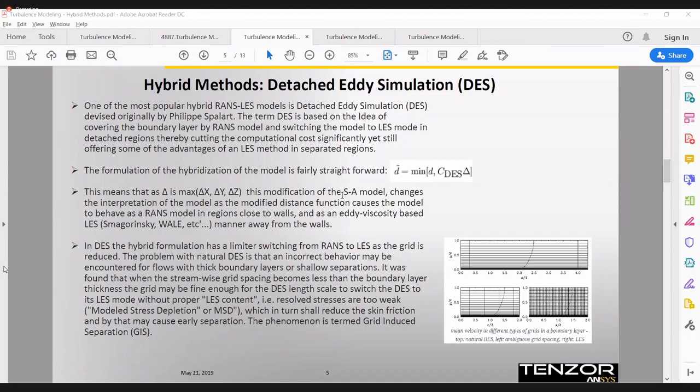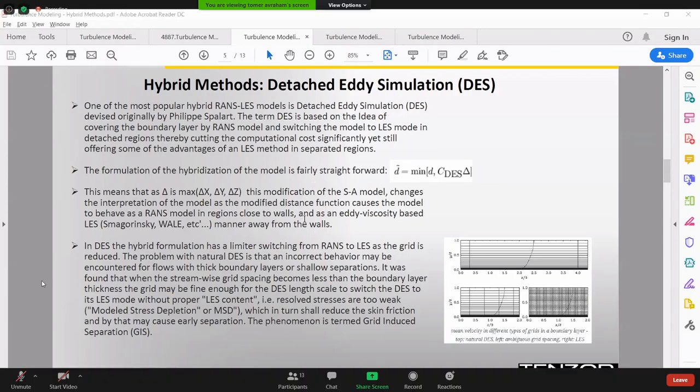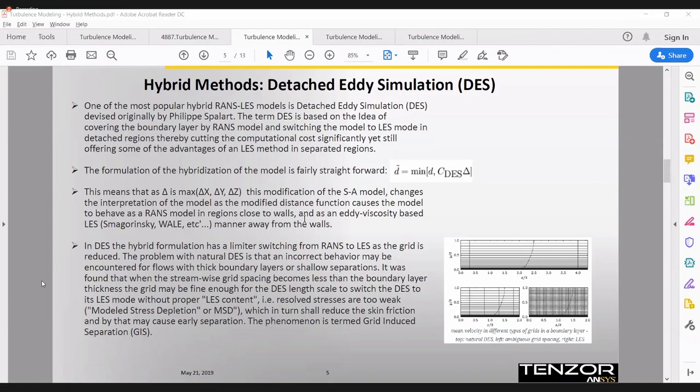It doesn't matter if it's Spalart-Allmaras or k-omega like in Fluent. We cannot promise ourselves that we are using a model which we can validate. You will not be able to validate it, at least not by higher moments or PSD or something like that.